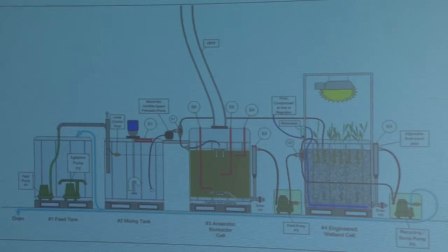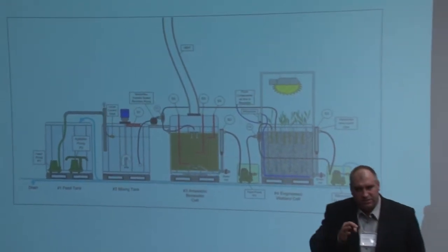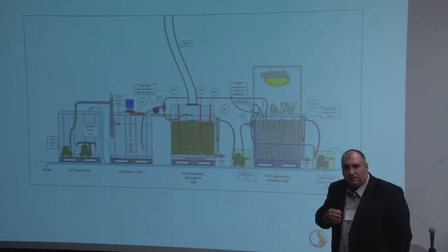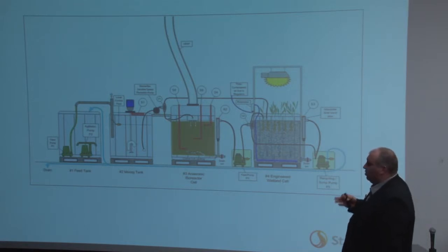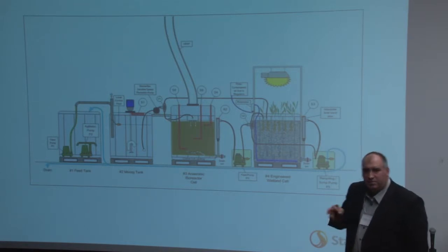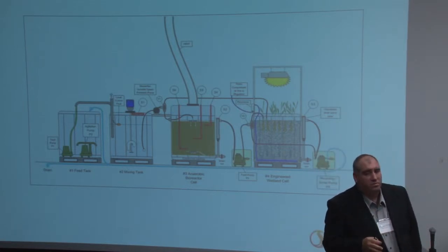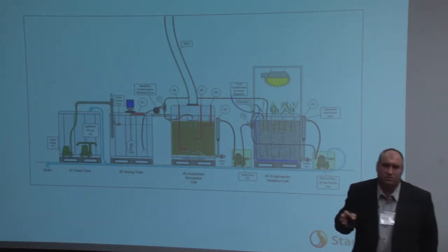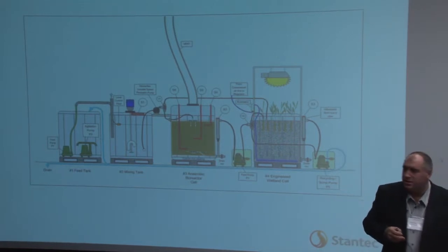It often starts on paper, where someone attempts to do some reaction kinetics and just kind of go through in a paper exercise to some level of proof of concept. From there, typically goes to a treatability phase, and the treatability phase often entails two things. One would be a lab scale bench test. These are often quite small, maybe 1 square meter, 2-3 square meters.